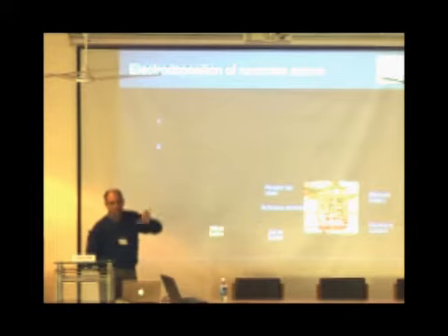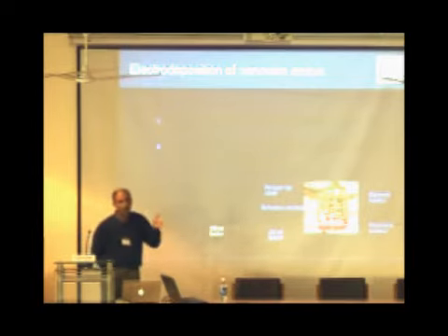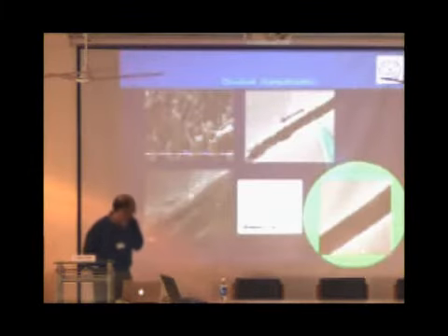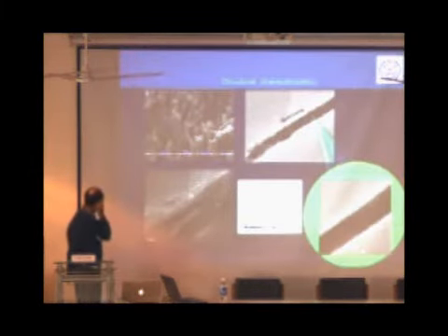It has a membrane where we apply a potential, which allows us to segregate two different metal ions. That allows us to modulate the rate at which layer 1 and layer 2 get deposited. These are the kind of templates we use, and these are the kind of nanowires we grow.